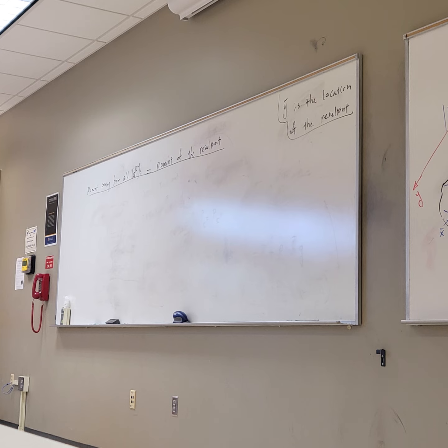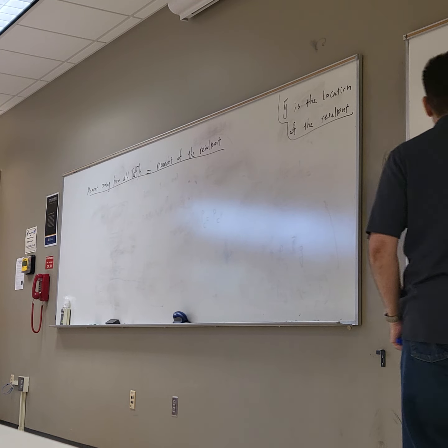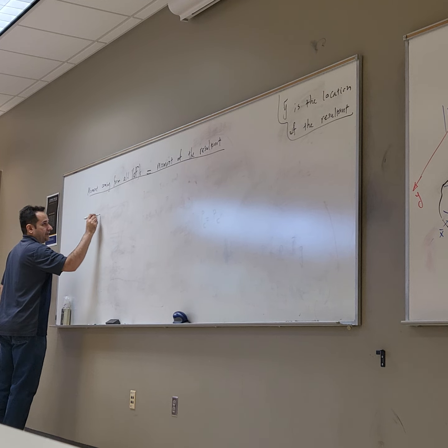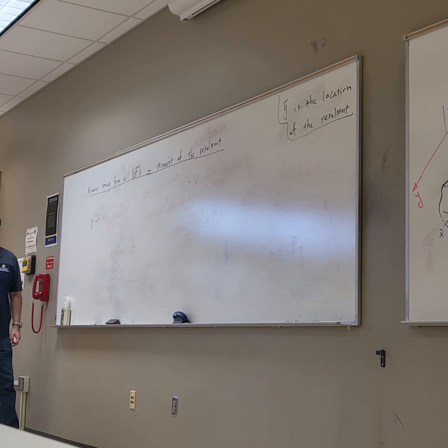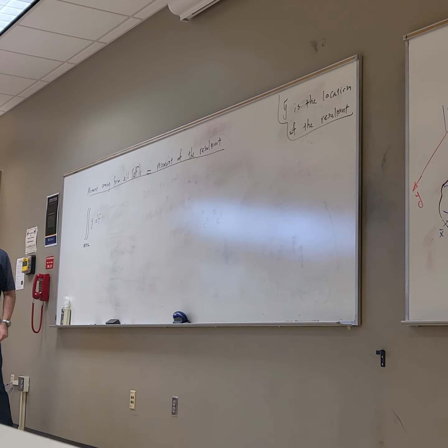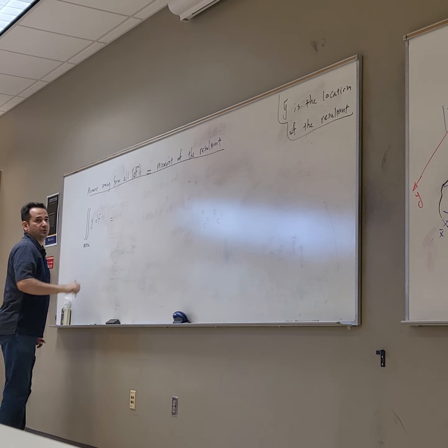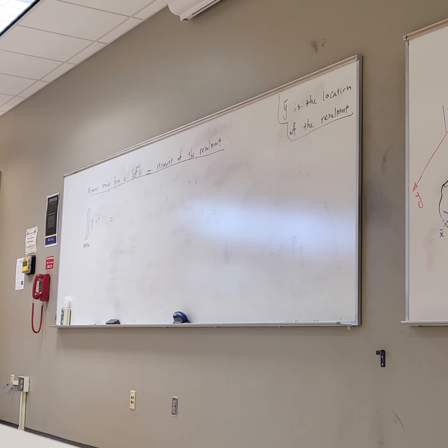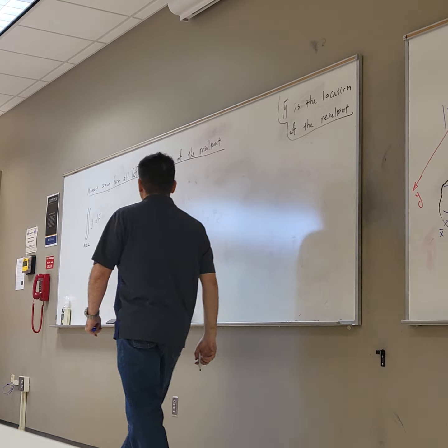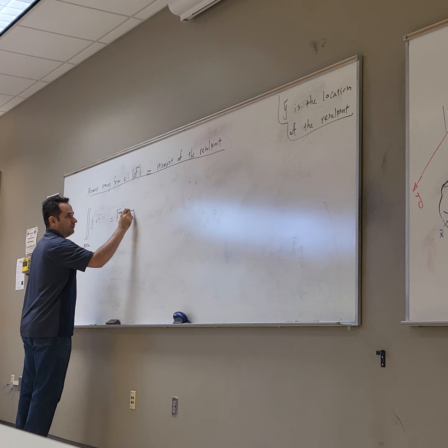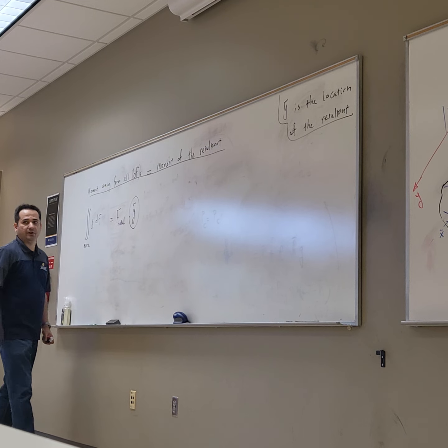And each one is acting at the location y. So the moment is y times df. And I have to sum this. How can I sum this? A double integral over the area. This is the net resultant moment coming from all infinitesimal df. This must be equal to the moment coming from F total times y tilde.